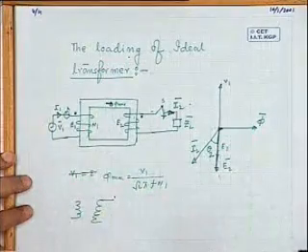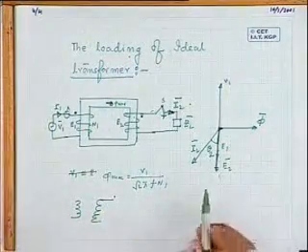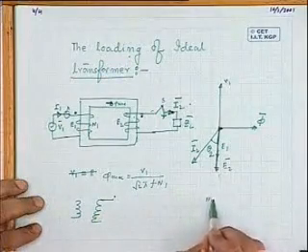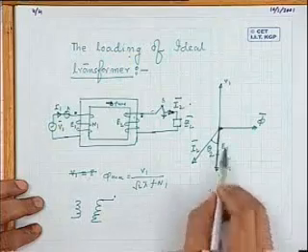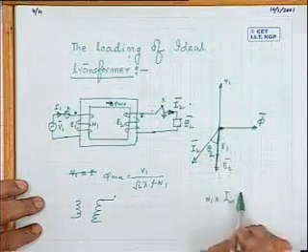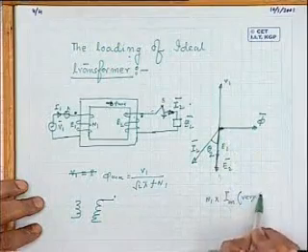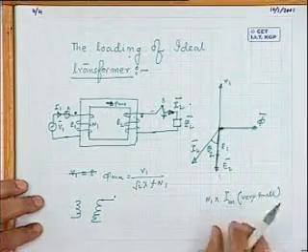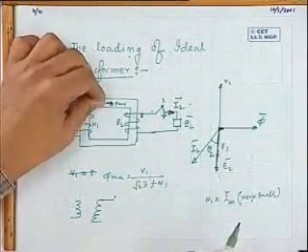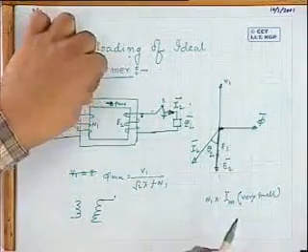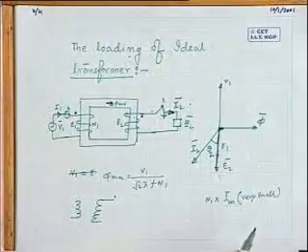See, earlier there was no secondary current. To produce phi max, how much MMF do you require? That is already known to me. That is equal to N1 into IM, this small current, which is very small. Are you getting? That MMF was acting alone and it produced phi max.